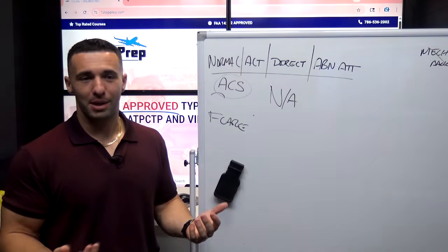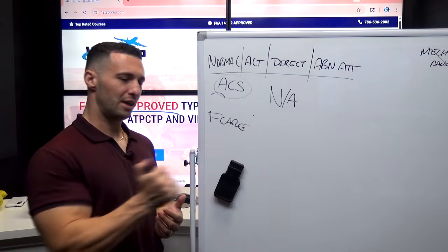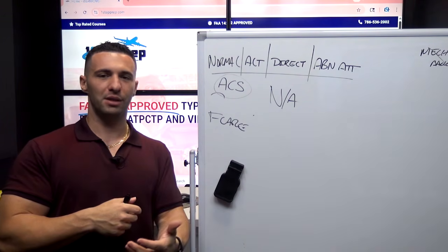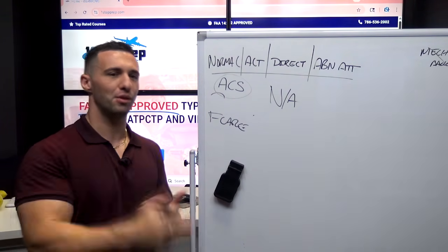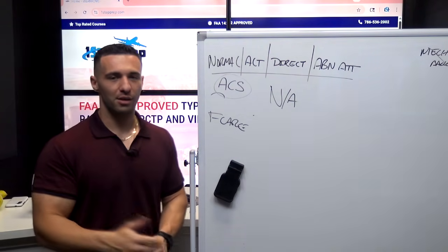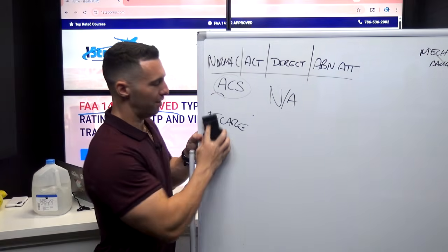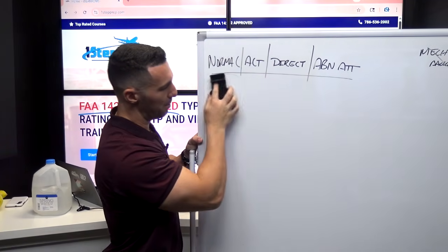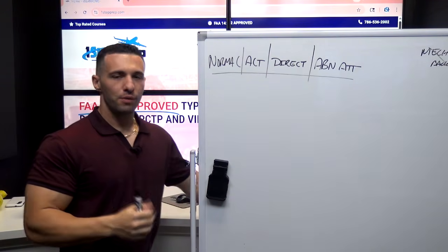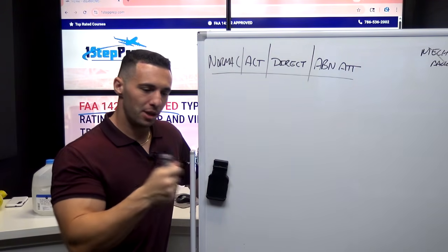Well, you're not. I mean, it appears that you are, but you very much put the needed input to overcome the flare mode and get going, and then all of a sudden the flare mode released, and so now you have excessive input, so you're having to adjust that accordingly, right? So that's another reason that you'll see this in the sim quite a bit, is this rejected landing at 50 feet happening.